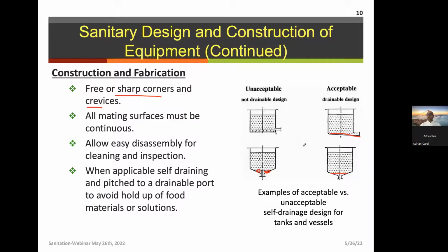And one of them is in drain design. If we have a system like this, then it is pretty easy for a biofilm to form, and that biofilm is going to start growing upward. If we are treating this, and then we have the typical crate that we have here, this biofilm can actually come out and start contaminating these zones in which we're moving around. Something as simple as that can create a lot of mayhem in facilities.